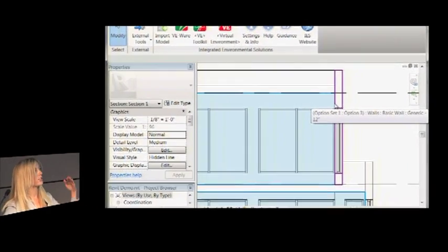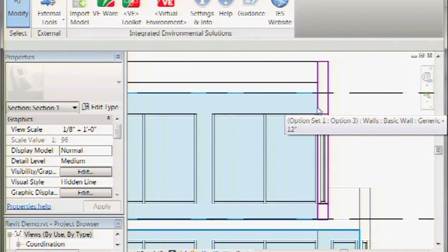So now it's going to start to cut in my space. So don't just think of making things non-room bounding that are in your horizontal views or your plan views, but also in your vertical in the space. Because you get that a lot with acoustical ceiling tiles that people drop in and those types of issues.